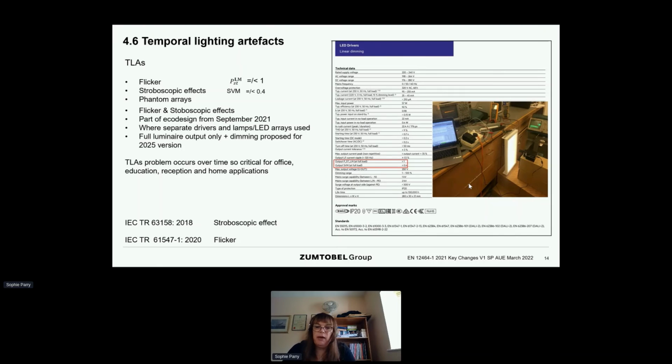That little photograph there on the right hand side is a customized luminaire that we built for a customer up at Thorn Lighting in Spennymoor, and the customer had flicker problems before and had been caught out and wanted to see a certificate for each of these custom luminaires. So there's one of the custom luminaires in the lab being tested. That little black box on the cardboard box has got a photodiode in it, and then there's a little snorkel on the front, so it's picking up the light just from the luminaire, and then it's going into some software which evaluates it for flicker and stroboscopic values.